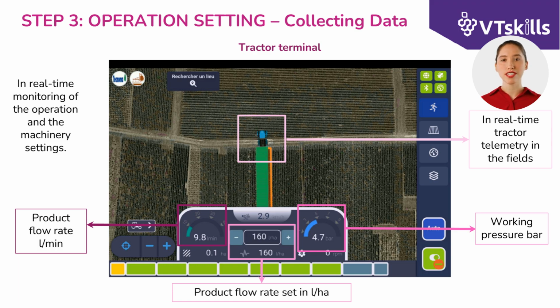The workflow involves the operator selecting a work area, generally a plot of land, and then entering the spraying operation with the previously determined parameters of application volume per hectare to be distributed. The system can then assist the operator in maintaining a correct forward speed or, in the more automated versions, intervene in the direct control of the sprayer to ensure that the theoretically planned volume is sprayed. Once the job is completed, it is possible to obtain descriptive summary data on work productivity and time. The operator can then use this information to improve their work by reducing inefficiencies such as breaks and downtime.